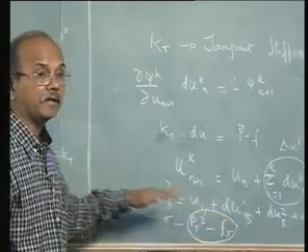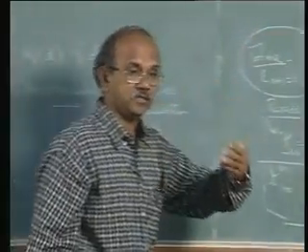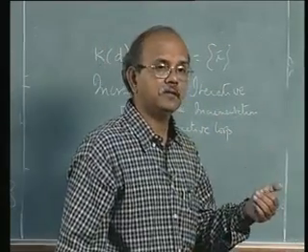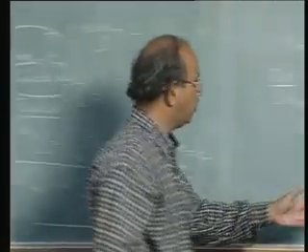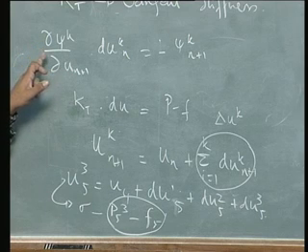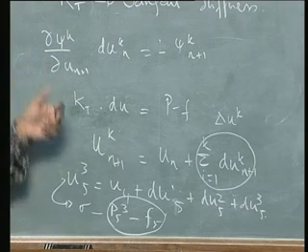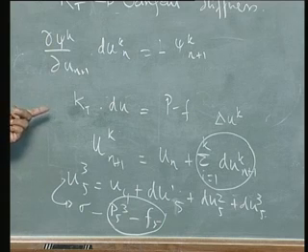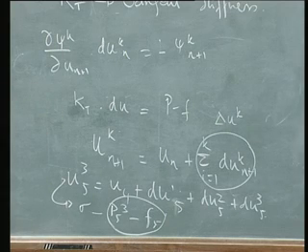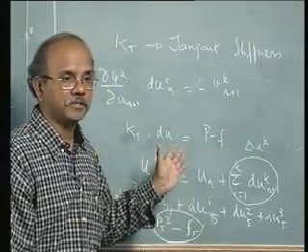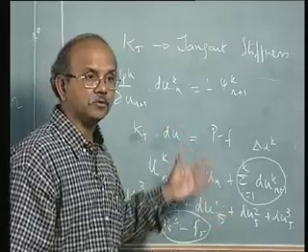Then we go back and go to the next iteration, the sixth one. Increase the load. If this is not small, what do we do? I get back to here, next iteration. That means I recalculate. What do I recalculate? Look at that carefully. Correct. It is the tangent stiffness that you recalculate. Then again calculate du, solving this equation, and then again do it.